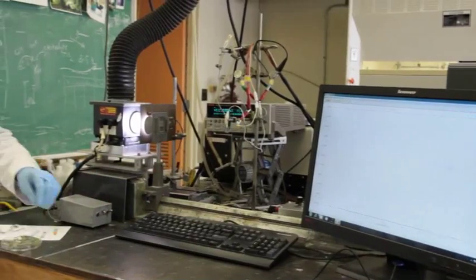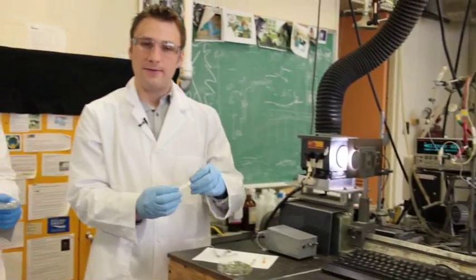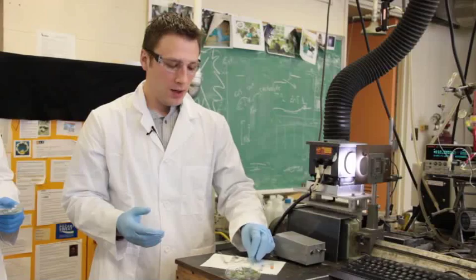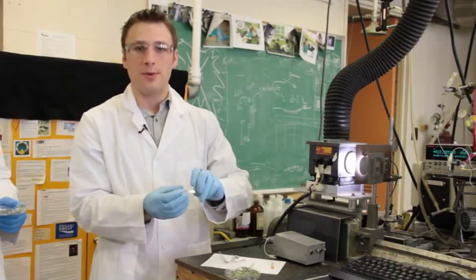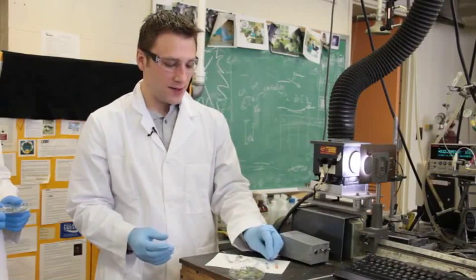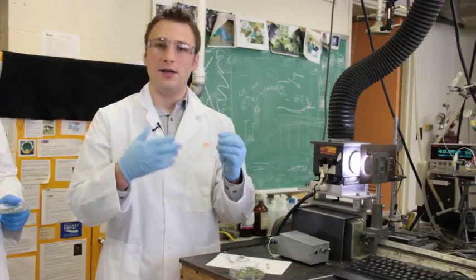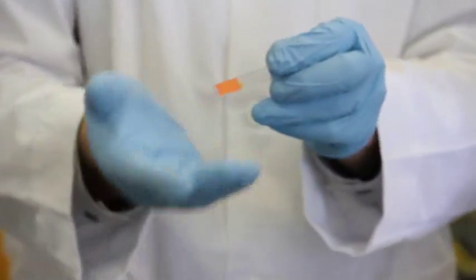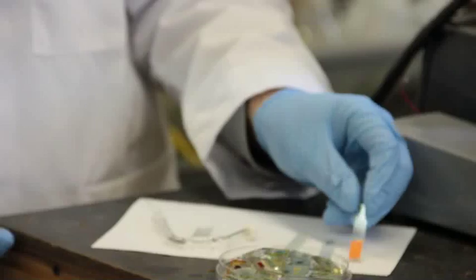Now this sort of setup is employed by first taking a conductive glass electrode on top of which we can put the graphene or carbon-based material. Now we can make that material sensitive to the sun's light by adding a solar sensitizer such as cadmium selenide quantum dots. Here the orange color comes from the cadmium selenide quantum dots.